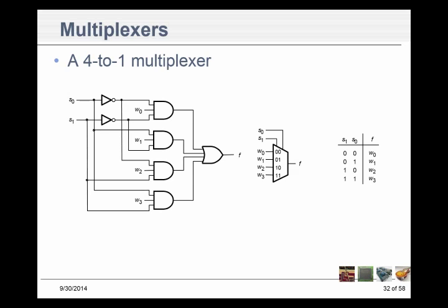It would if it was an OR gate. What would W0, 1, 2, and 3 have to be? 0, 1, 1, 1. And then those selector bits would choose which one of those bits appears at the output. So if we had 0 for this and a 1, 1, 1, we have an OR gate. What if we had for W0, 0, this we had a 1, this we had a 1, and this we had a 0? What would you call that? 0, 1, 1, 0. Exclusive OR. So it looks like we can create just about any kind of chip you want to create.